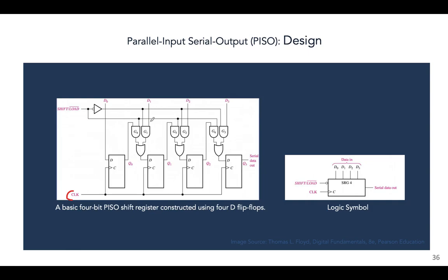And this is what actually makes a PISO register work. Because again, remember, the thing about PISO registers is that the data comes in parallelly, that is, the data is loaded into the register simultaneously, but it must be taken out serially. And these gates are actually what makes it work, right? So this will become clearer in just a moment.